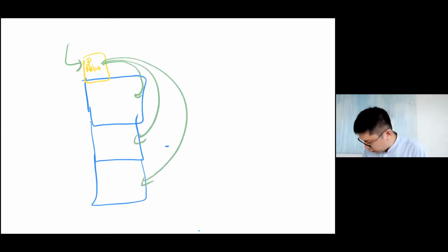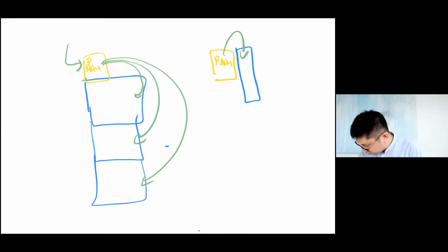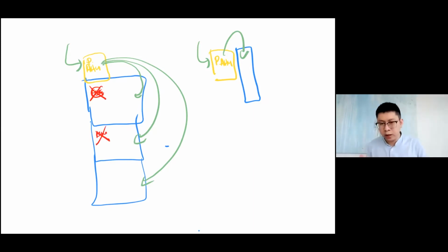Or it can be a single zone as well, but fully served by the PAHU, which means it doesn't have FCU or AHU in here. So it primarily depends on the primary AHU. The primary AHU doesn't have recirculation. The function of the primary AHU is just to take in outdoor air, treat it, and then supply it to the area.